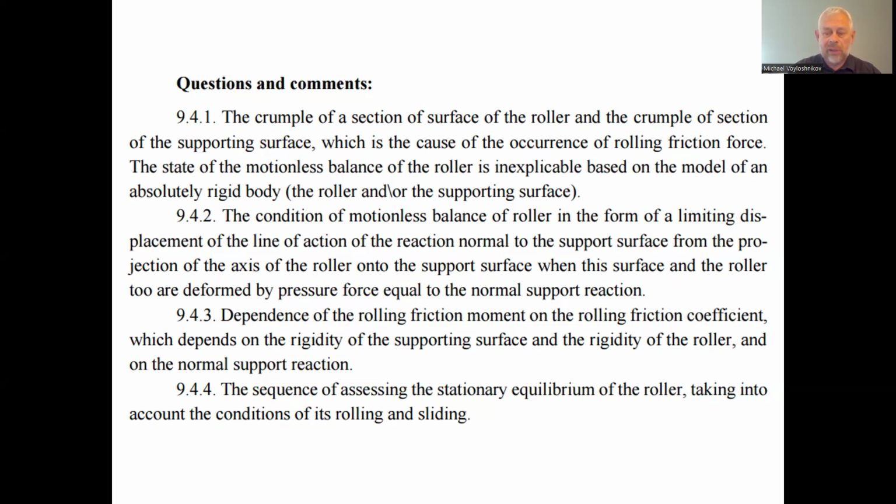of the roller with the definite factor of resistance to the roller rotation, proportional to the maximal arm of the shifting of two parallel forces: the vertical component of all forces with the weight acting on the roller on one hand, and the vertical component of the support reaction on the other hand, when they are not on the same line. So when the line is shifted, the points of application, due to the deformation of the support surface and the deformation of the wheel, can cause the resistance.